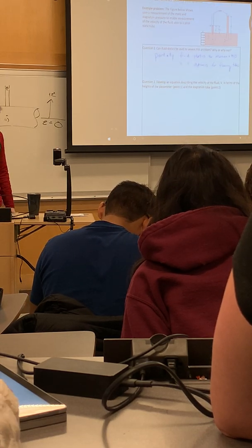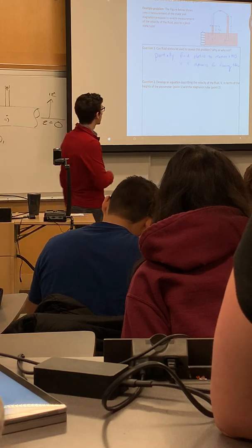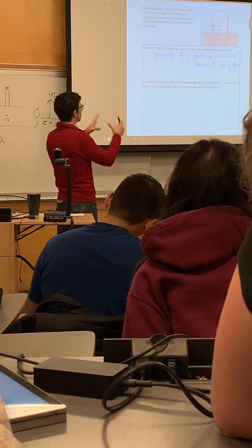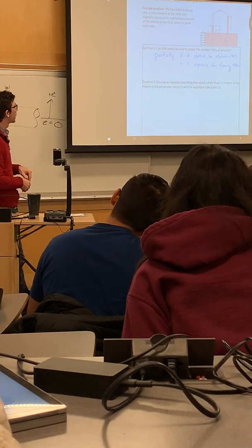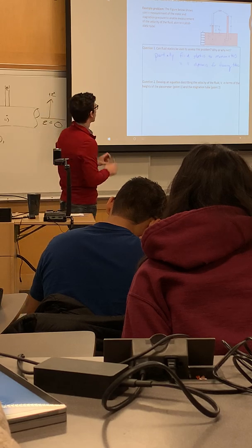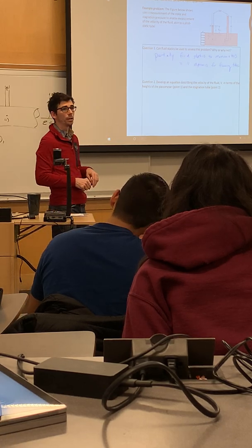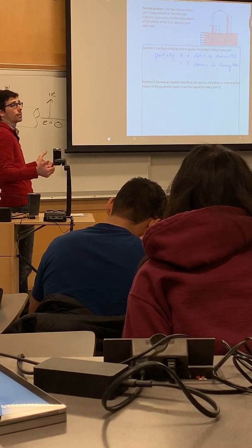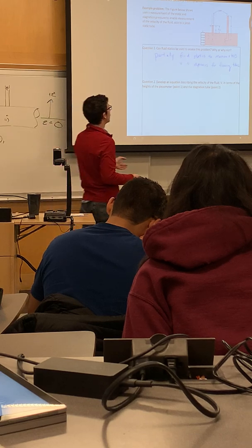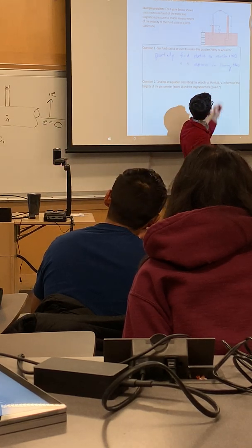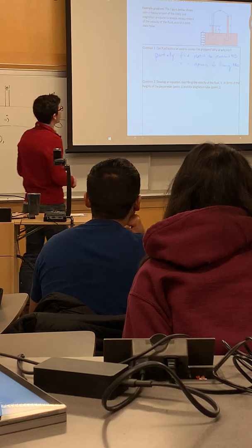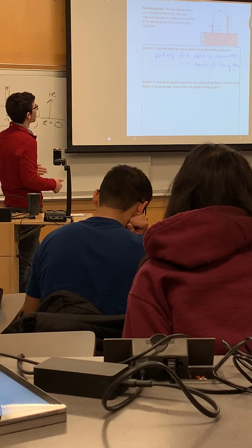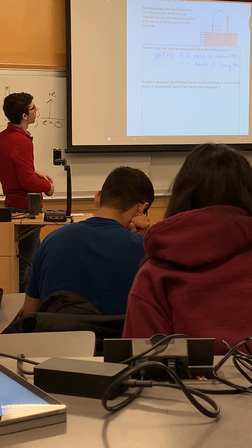So some of these convenient points are set up for you. It's similar to the example we talked about previously. If you see things that stand out in the graphic, like something attached to your fluid, it's probably a convenient point to drop a Bernoulli point, because you'll be able to get more information about the fluid at that point than you would in between these two vertical tubes, right? So this problem helps you a little bit by indicating point 1 and point 2 and some of the descriptors of the fluid at those points.